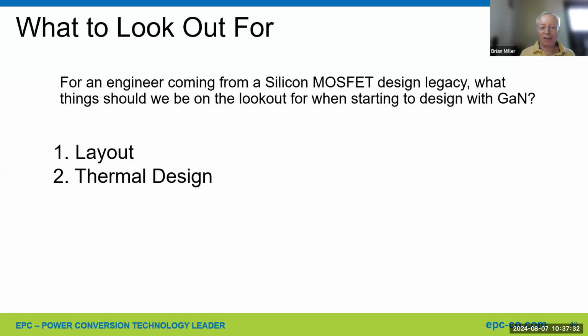Thermal design. That's something that is key. GaN FETs have very good conduction to the top, but because they're small, using the thermal calculator EPC has and looking at some app notes can really help in doing good thermal design. GaN FETs conduct heat through the top, also from the bottom, but because the top area is larger, they conduct better out the top.